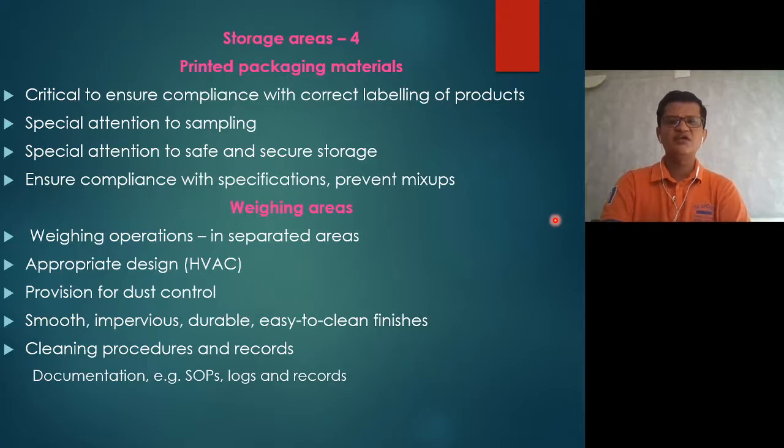Now, the weighing area should be in separate areas. There should be HVAC on it, so there should not be any chance of microbial contamination. There should be a provision for dust control, and it should have smooth, durable and easy to clean finishes.